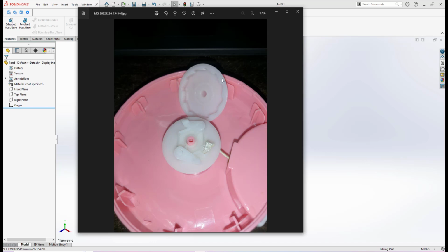This internal gear has internal teeth, and it will be mounted on top of this pulley and also these two latches. Once we pull the handle, these latches will drive that internal gear. These latches act so that when the rod is rotating, when the cutting blade is rotating, it can have kind of like a freedom of rotation movement. That's why they use this kind of latches. All right.